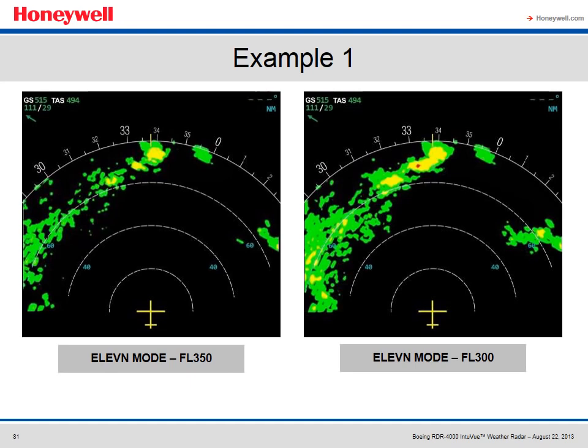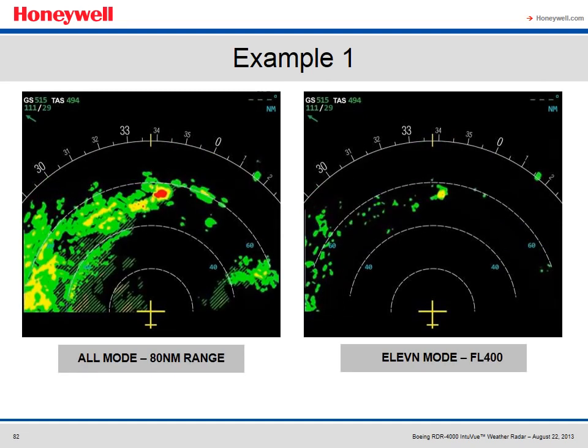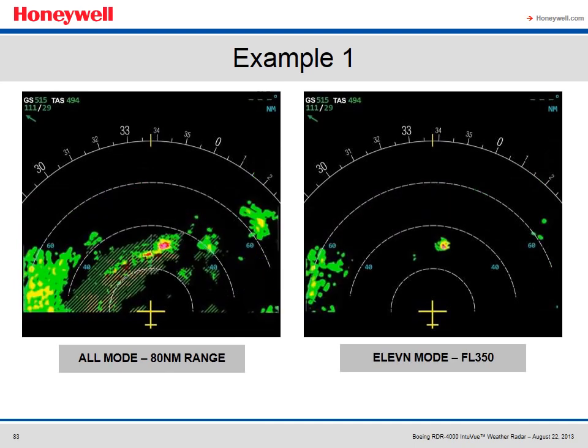However, there is some weather to the right coming into view near the deviation path that will need to be monitored. 20 miles closer, the cell on the right is showing much more reflectivity, and a look at an altitude slice shows it is the only cell that is a hazard at the aircraft's flight level. The weather to the right of the two cells in the deviation path has developed into nothing of interest. When the cell is at a range where turbulence can be measured, additional evidence comes into view, the magenta color, indicating the cell on the right is the most important one to be avoided.